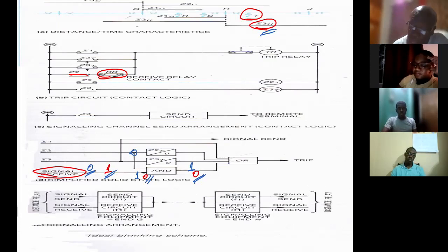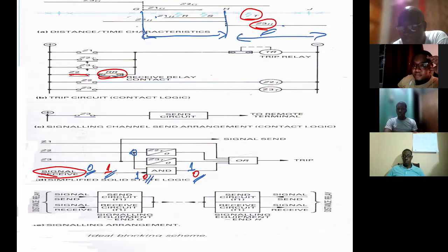All right? So what we have here is that because the fault is outside of the protected line, this line would remain in operation. And it would allow the protection on the adjacent line to operate. You see, everything has to tie up. So what we spoke of when we mentioned the whole business of discrimination, remember all of that?